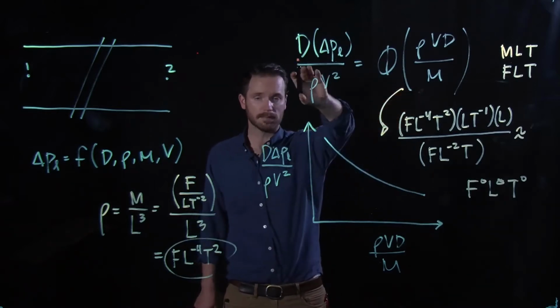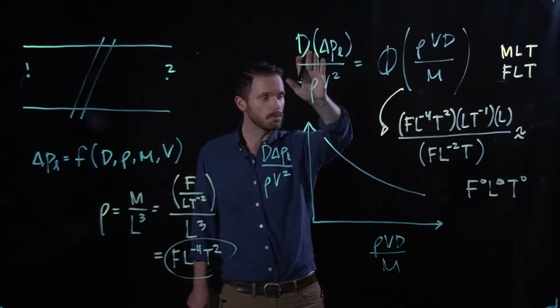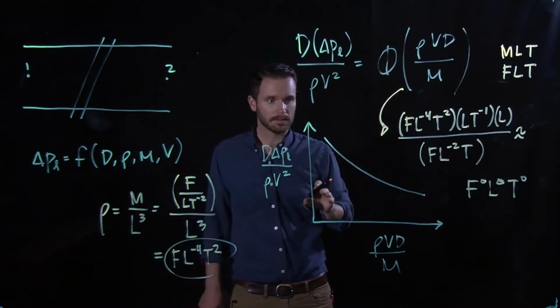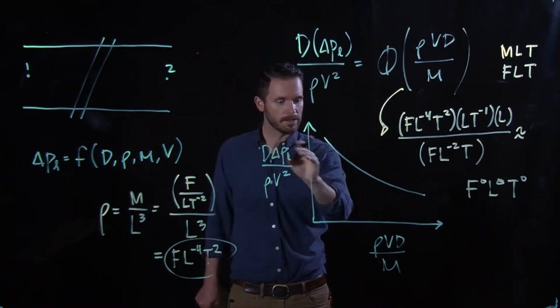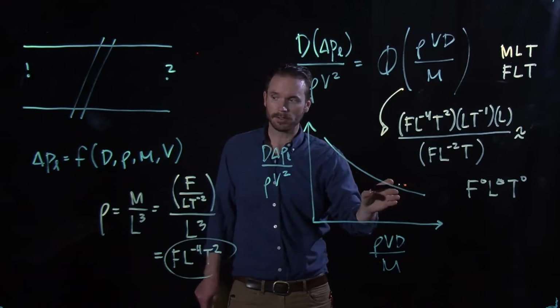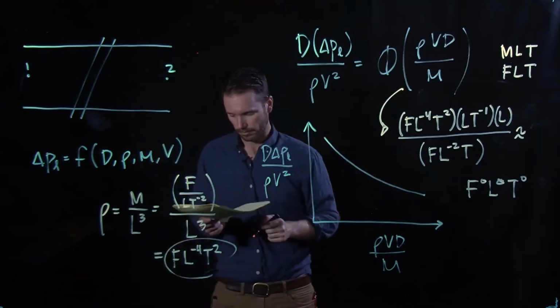We could do the same thing for this dimensionless variable, and we could say there are no units associated. So this would be two dimensionless parameters, and this is called dimensional analysis: the ability to equate these two parameters and find the function that describes them, which in turn makes our lives much easier than if we had to do this for 5 different variables.